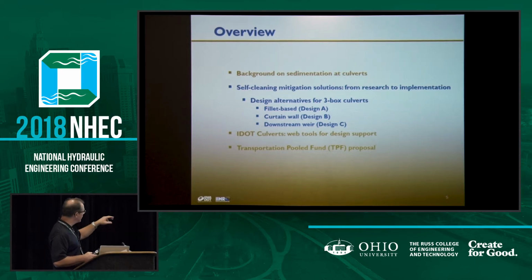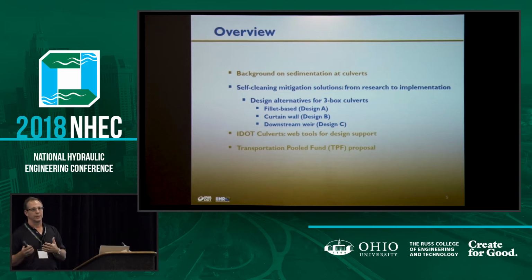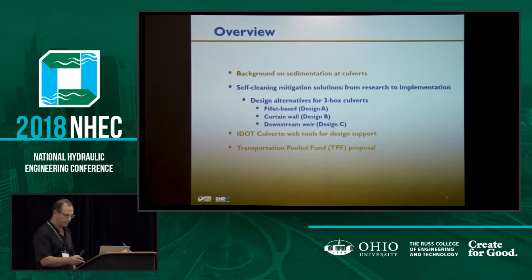Then the other 2 are things that came up as the University of Iowa and Howen and others were looking at these sites: this curtain wall method and this downstream weir came up as possible mitigation measures that could reduce sedimentation in multi-box culverts.